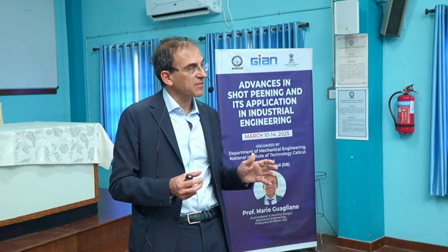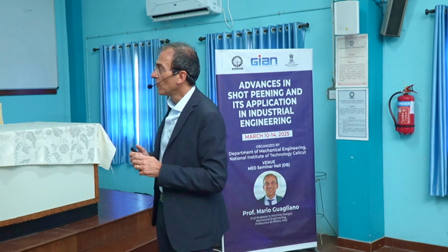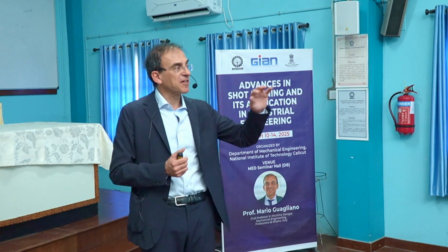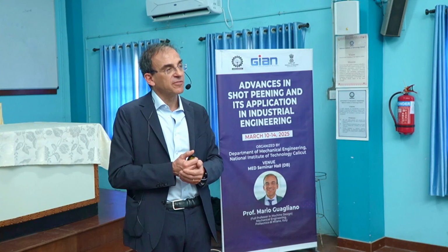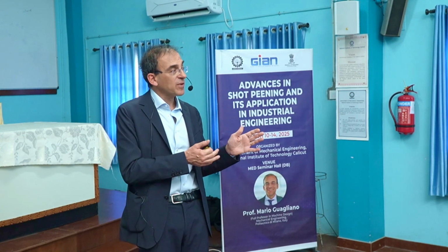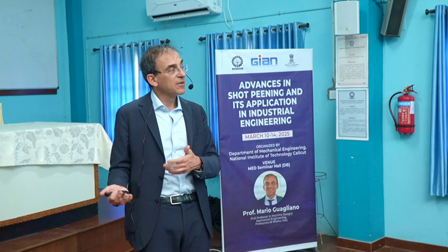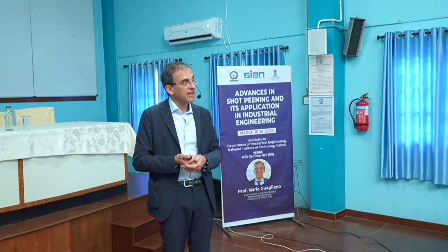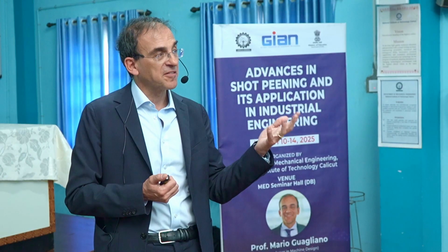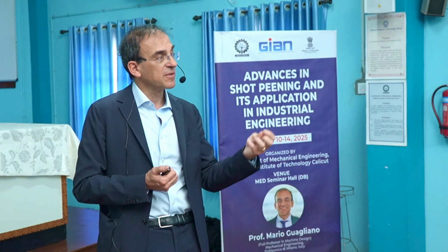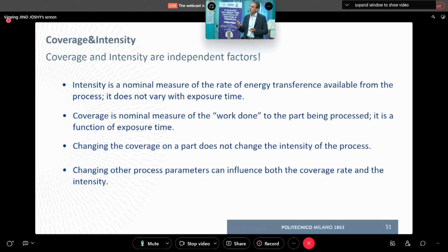These are two different things. Also, the time that we use for assessing the saturation condition for intensity is quite different with respect to the time we need for assessing the coverage. And do not forget the intensity is checked by using a strip, while the coverage is checked by using the workpiece.